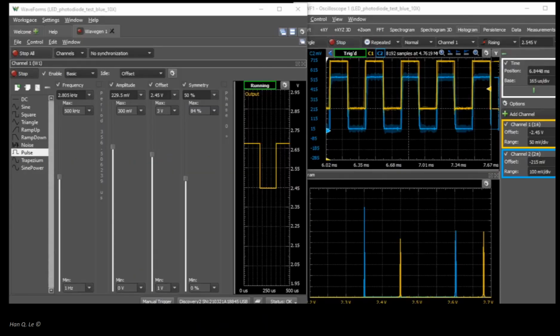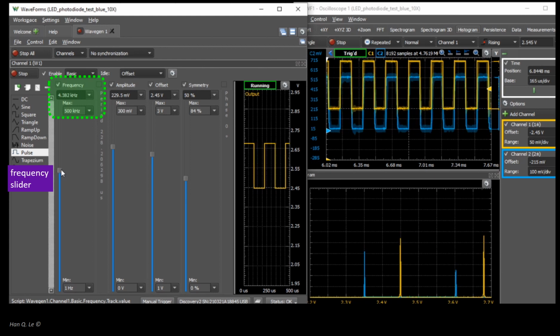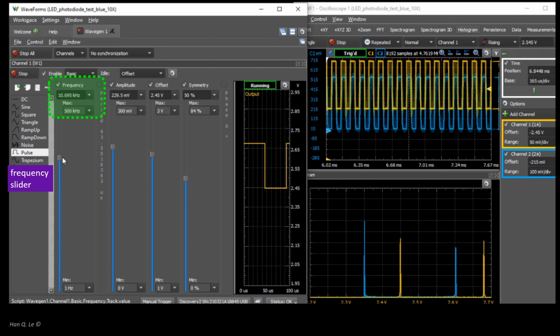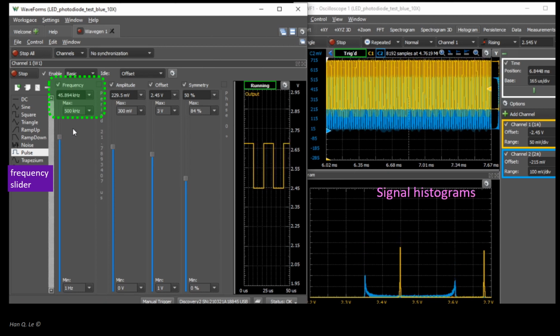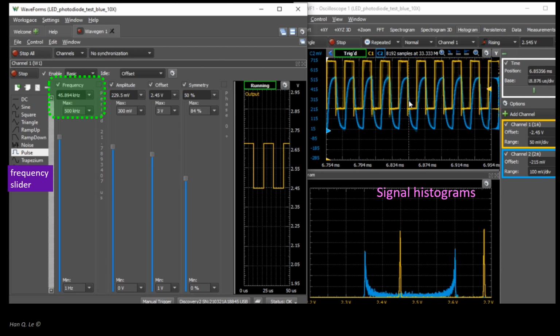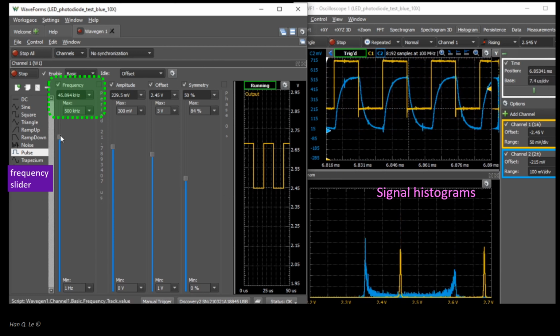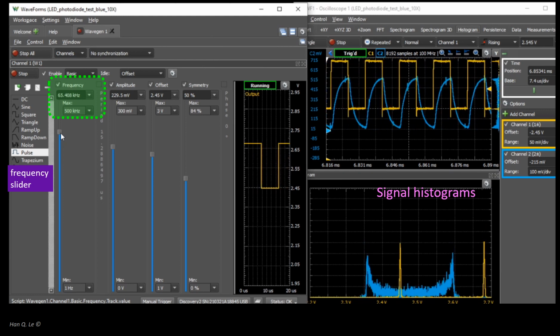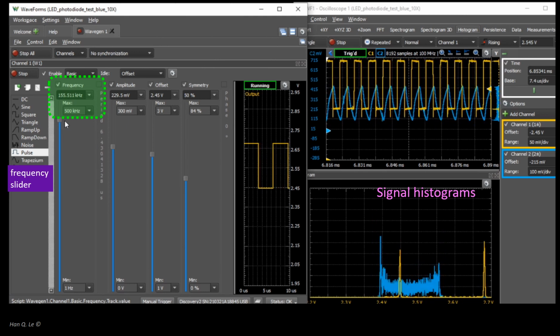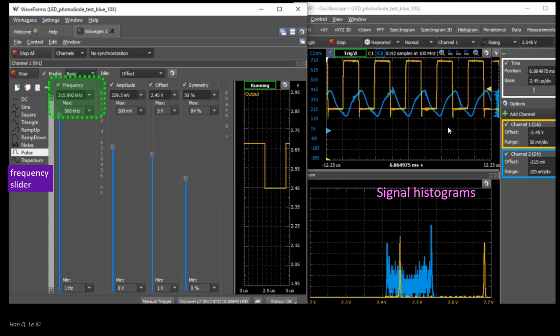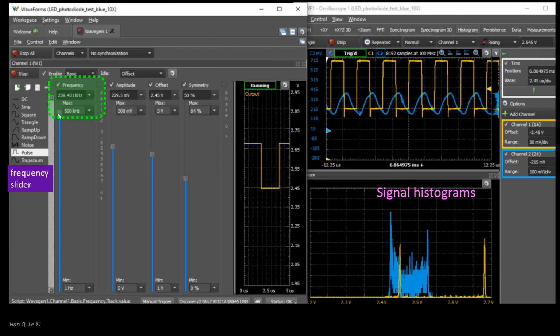The transmitter-receiver signals were studied as a function of frequency, which varied from approximately 3 to 260 kHz. As the frequency increases and the pulse shortens, the signal starts to have roll-off, its rising edge and falling off tail come close to each other, resulting in the pulse shape change. The histogram shows that the signal pulses cannot maintain the wide gap between high and low levels as those at low frequencies. The rising edge of each pulse never reaches the full height, and the falling off at the end of each pulse never reaches zero. The signal histograms indicate that the output drops to a half, or 3 dB, around 250 kHz.